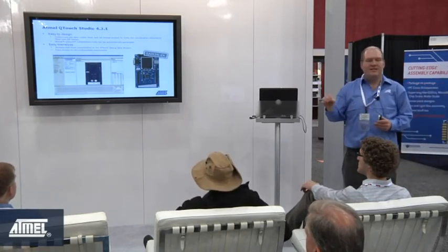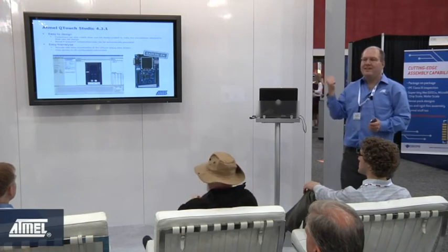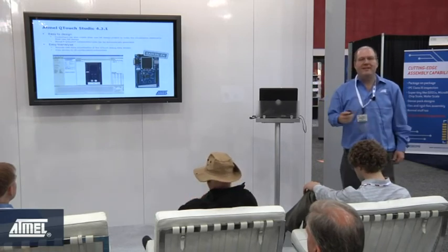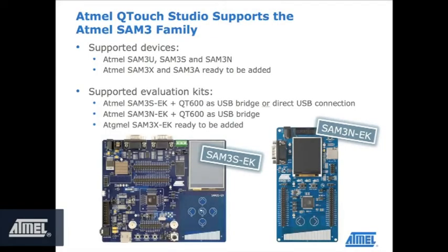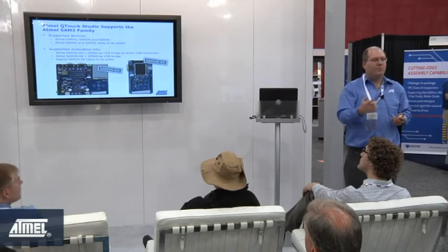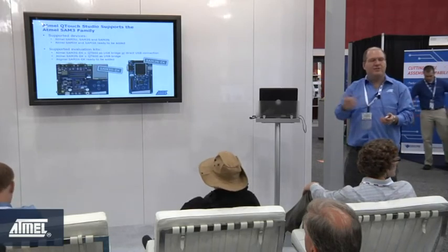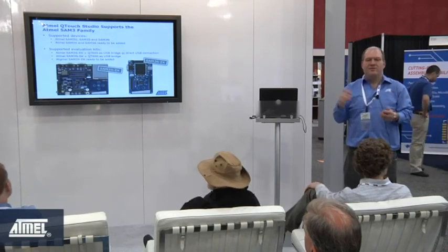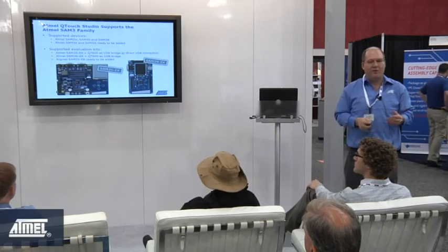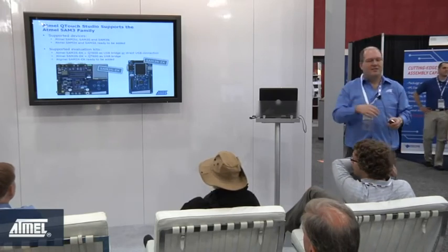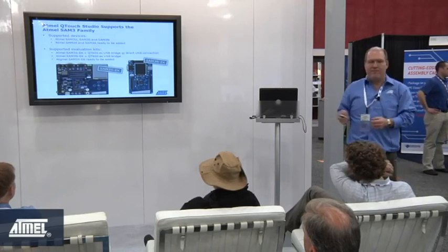So you don't have to sit there and wade through a bunch of data sheets and figure stuff out. The software does it, and it does it customized to how your hardware's been laid out. This QTouch Studio, again, supports the SAM3N EK and the SAM3S EK. And the basic concept is a kind of feedback loop. After you get your board done, we also supply a tiny little program that runs on the microcontroller, which provides this real-time application support, which gives you the feedback back into QTouch Studio, which tells you your performance parameters and how good your design is. And again, you can tell it to generate your API calls from those design parameters.